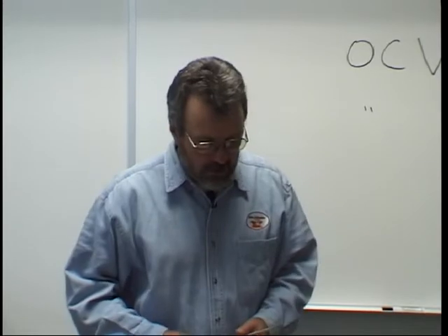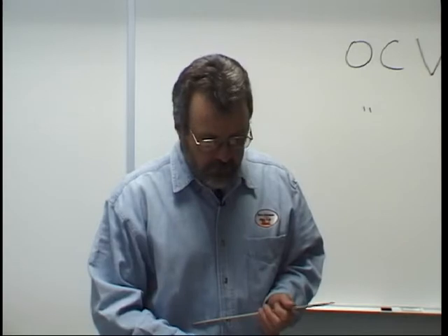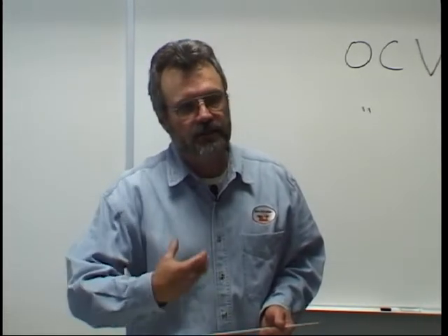The question I'm going to ask here is about the alloying elements. The fluxes used are intended to replace that stuff so that you can come up to the properties of the base metal. So there'll be a question out of there. Deoxidizers, I'm not really going to ask you about, but the whole purpose of the alloying elements is, again, to get back to matching the mechanical properties of the base metal. So if I ask you why you would want to put alloying elements into the filler wire, well, to match the mechanical properties of the base metal.